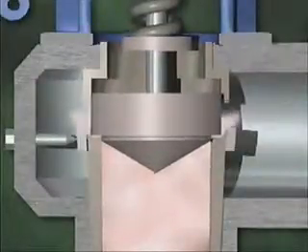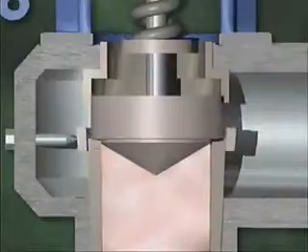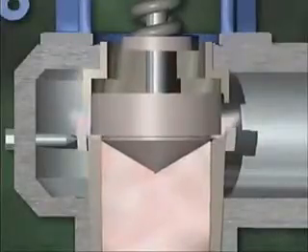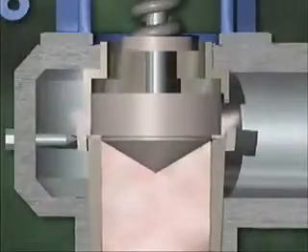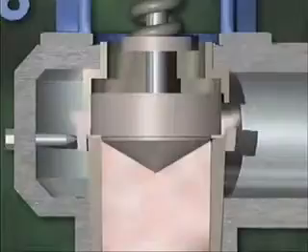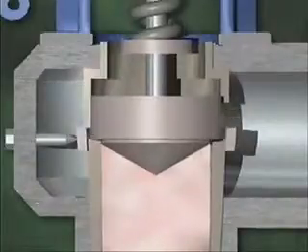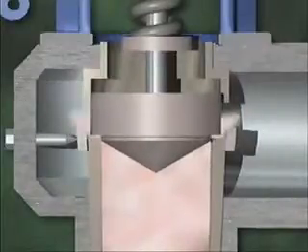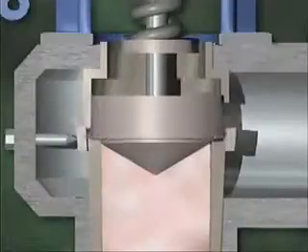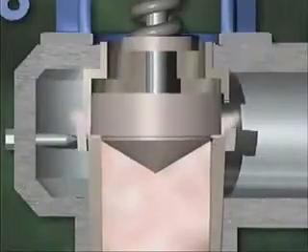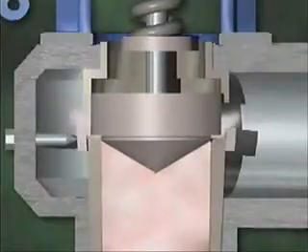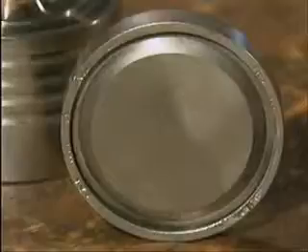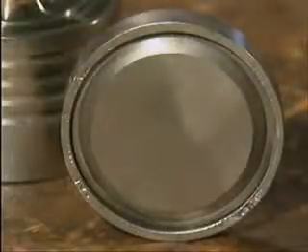Adequate blowdown helps prevent a condition called chattering. You see, if there's no difference between a valve's popping pressure and its seating pressure, the valve disc will jump up and down on its seat until pressure either increases enough to pop the valve open again or decreases enough to keep it closed. This condition is called chattering because of the sound that the disc makes as it moves up and down. Chattering can seriously damage both the disc and the seat because it promotes steam cutting.